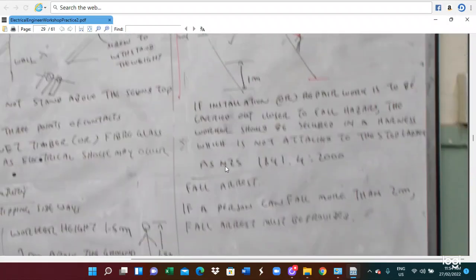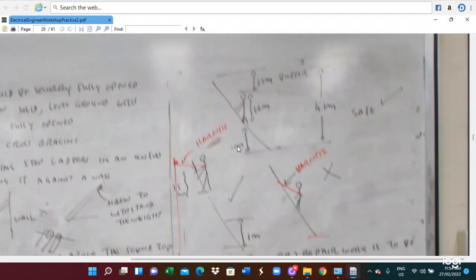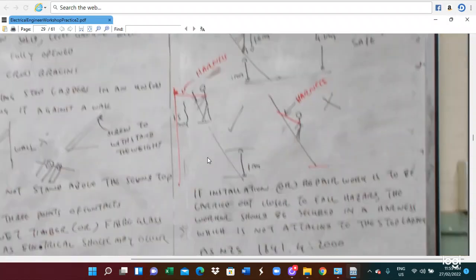So here you use a ladder. This is 1 meter here, 1.6 meters, and a 1.5 meter buffer zone. This is correct, so the total is 4.1 meters. Worker height is 1.6 meters, 1 meter above the ground, and 1.9 meters buffer zone. If you are working in the buffer zone, you must use a lifeline safety system, which is attached to other fixed installation, and then you can utilize it. So this is where the harness wire is connected.